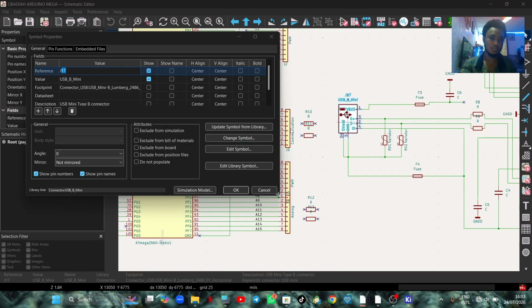So you search for a footprint in the pop-up option. When you click on it, you see that it already has a footprint here. When you click on the three dashes here, the footprint has to appear. So we wait for a while for the footprint to appear.